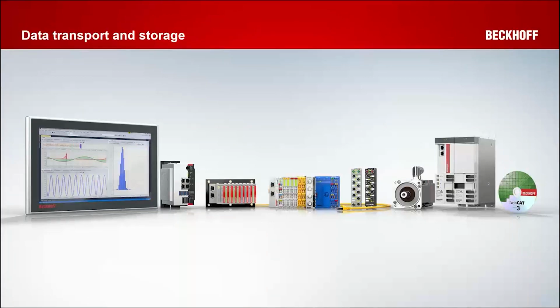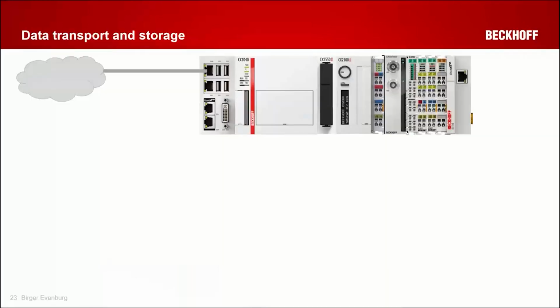Next topic is the data storage, how we can store the data. In this example, we have a CX, which is configured with an operating system, TwinCAT is installed, and a FlexMeter project is activated on that device. Here we have an SSD extension kit, so we have more space to store the data directly on that system. So maybe we do not have a network connection, or the network connection is not fast enough to handle 50 kilohertz sample rates for a couple of channels. So we can store the data directly on the machine.